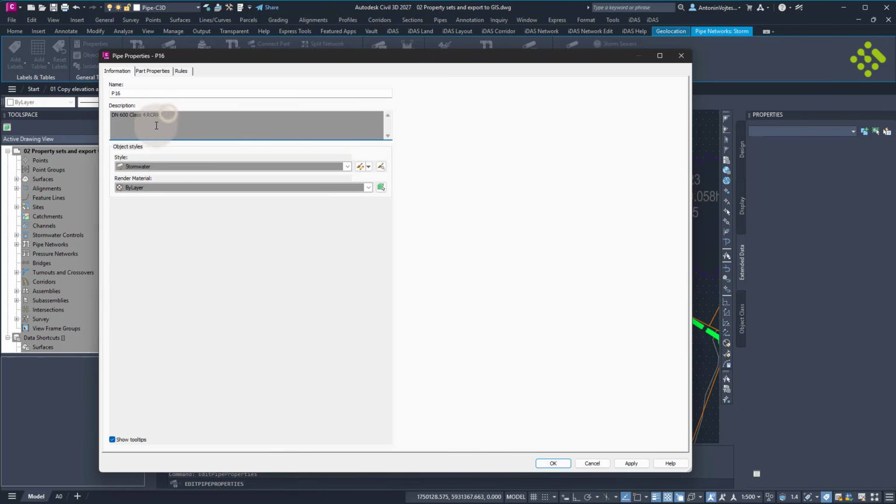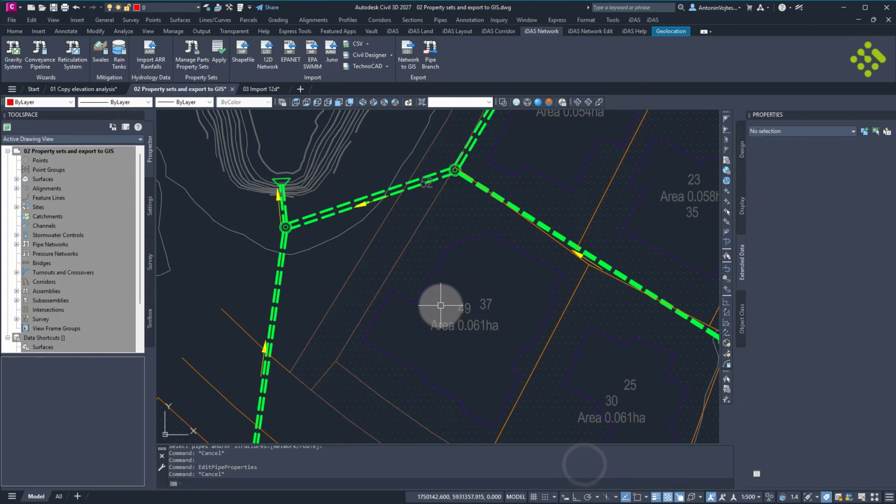Or let's say other clients don't want to display reinforced concrete RCRRJ, they only want to display RRJ. So how to fix that? I will select RCRRJ and I will copy it to clipboard. Then I click cancel.